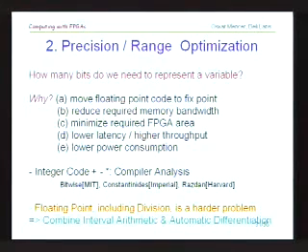And we can therefore also decrease maybe power consumption. So these are all ways to try to optimize an inefficient implementation on the FPGA. And once you can optimize more than you lose with the FPGA, you actually have a better implementation than you have on the microprocessor.